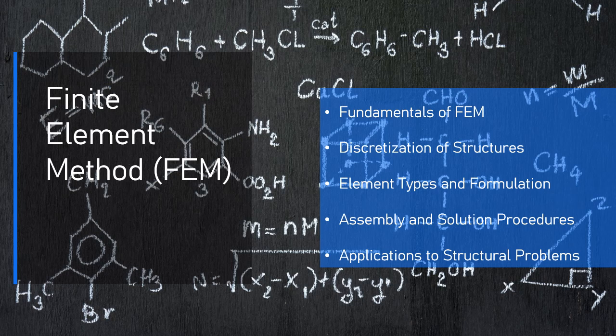3. 3D elements, solid elements. 3D elements are used for volumetric structures or solid bodies, where all 3 spatial dimensions contribute to the deformation. These elements are used for bulk structures or volumetric problems, such as pressure vessels, complex 3D components, and other structural bodies. Examples: tetrahedral elements, 4-node 3D elements that are typically used for meshing complex geometries. Hexahedral, brick, elements, 8-node 3D elements commonly used for modeling solid structures.